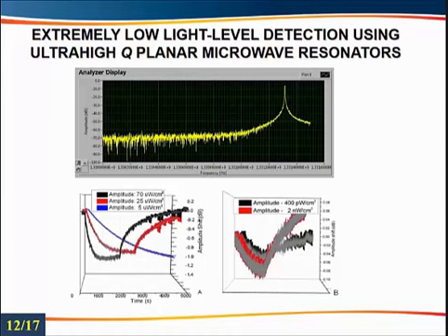using a UV photodetector based on single crystal zinc oxide nanowires in a typical conduction based photodetector was, I believe, 5 to 10 nanowatt per centimeter square, and in basically a very first attempt we were able to reach 2 nanowatt per centimeter square detection limits for UV photons because the quality factor was so high.